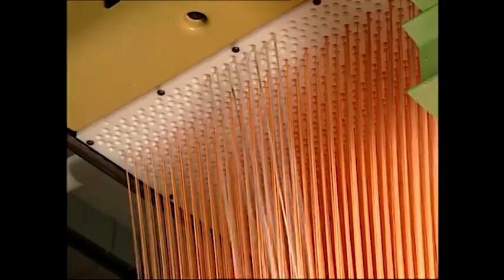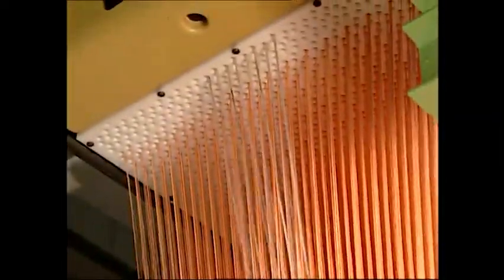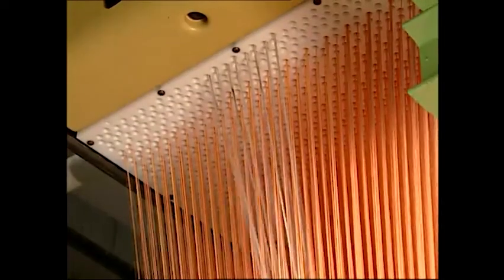Fabrics made on jacquard looms are normally more expensive because of their complexity and slower weaving speed. There are no harness frames on this style of loom. Each end is activated independently, being controlled by its own harness cord from the jacquard head. The harness cord is attached to a heddle, which is pulled down by a spring in most cases, but in some of the older and slower models, weights are used to pull the heddles down to achieve the pattern.